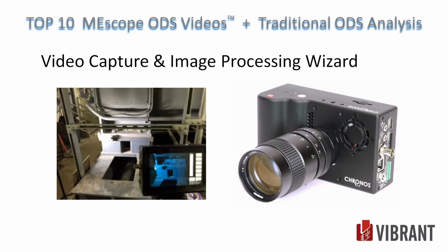Actually, no. The video is pixel motion. So you'd have 1.3 million or so pixels on the display, and all those pixels are moving. The traditional ODS is an accelerometer, so you'd have maybe 100, 200, 300, depending on the size of the machine, measurement locations, and you'd get a much sparser look at the data, but the overall motion is pretty clean. No, but you can't mix the two. You do one or the other or both. And typically I do both. I'll do a video and then I'll do an ODS animation as well.